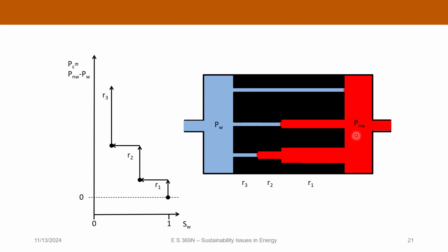Okay. Now, if you do the opposite, if you do the whole process in reverse, where you reduce the pressure of the non-wetting fluid, it would just follow the same steps exactly in order, and so go exactly back down the same capillary drainage curve. The reason that happens is because these pores all go in order of decreasing size from right to left, so there's no mechanism that would trap the non-wetting fluid in there. We talked about this again for CO2 storage.